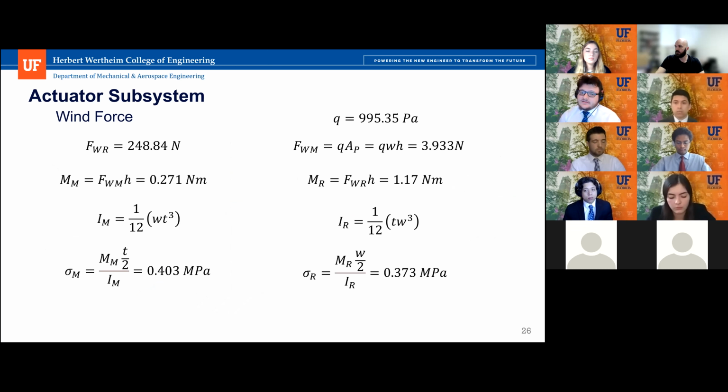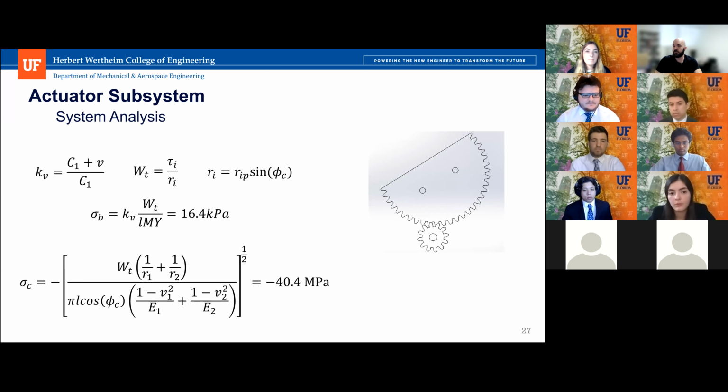The only other one is if wind comes from a perpendicular direction to the reflector, it would act on the small vertical face of the mounting bracket you saw, inducing the other force. Respectively, the force of the wind on the reflector and the force of the wind on the motor mount. And we find it survives plenty. We made this out of steel, so it has a high yield stress to withstand this for the full operating lifetime. We can move on further.